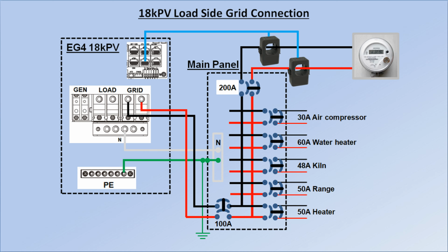With this system in place, there's no need to upgrade a 200 amp main panel or derate the 200 amp main breaker. Based on my town's PV permit application, I'm going to have to educate the building inspector and possibly the electrical inspector by covering all this material with them. Maybe I should just simply ask them to watch this video before they're evaluating my permit.